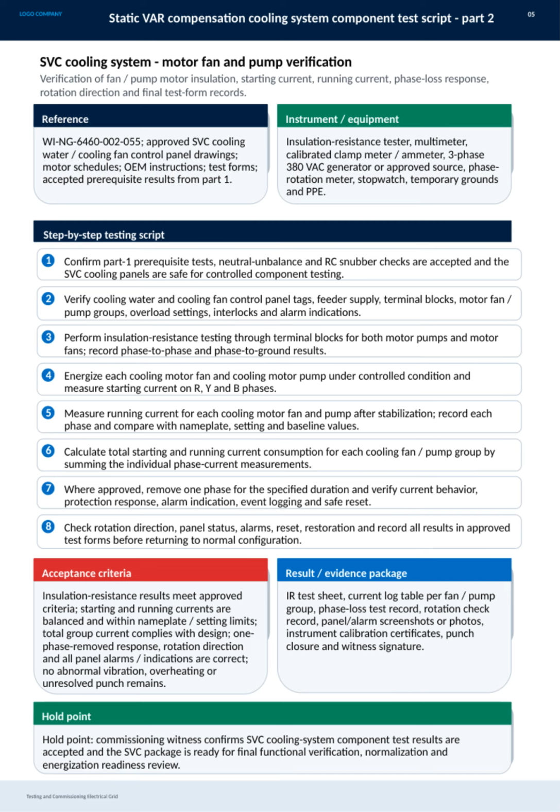We start by confirming that all prerequisite tests from Part 1 are accepted and that the cooling panels are safe for controlled testing. Next, we verify all control panel tags, feeder supplies, terminal blocks, and interlock settings to ensure everything is correctly configured.